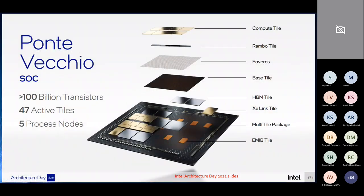Moving from 2.5D to 3D, what you see in this picture is a true 3D integration where you actually integrate one chip on top of the other one. The example I'm using here is an Intel Ponte Vecchio SoC. Intel Ponte Vecchio has more than 100 billion transistors. It has 47 active tiles. All these tiles are actually chips on their own. So you have 47 different active tiles, and they are fabricated using 5 different process nodes.